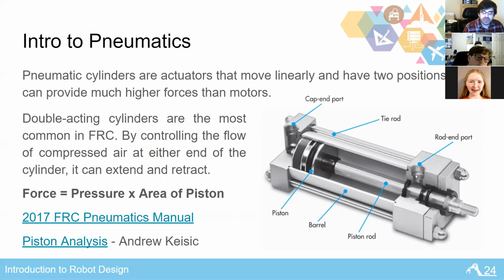So the larger the piston is, the more force, because the force is the pressure of the air, which is 60 psi or lower, multiplied by the cross-sectional area of the bore of the cylinder. And so small packages can get some really high forces, which is good.